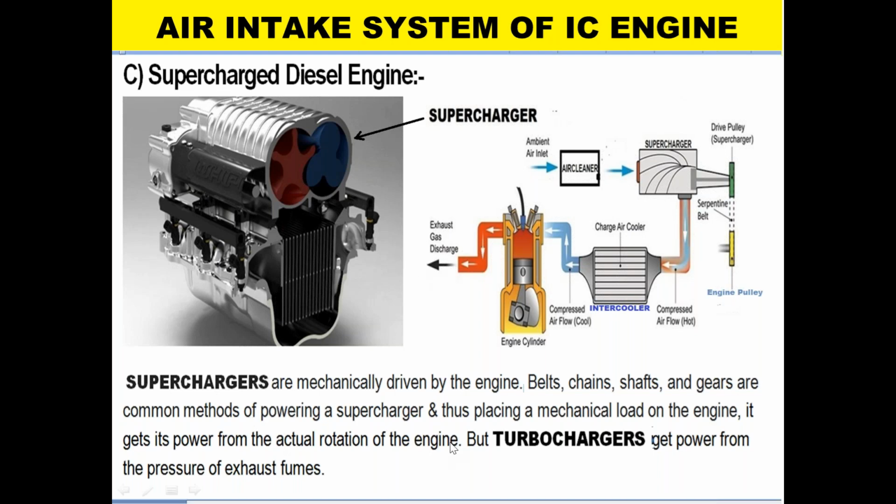Superchargers are mechanically driven by the engine. Belts, chains, shafts, and gears are the common methods of powering a supercharger, thus placing a mechanical load on the engine. It gets its power from the actual rotation of the engine. But turbochargers get power from the pressure of exhaust fumes. The superchargers are fitted in racing cars as well as big commercial vehicles.